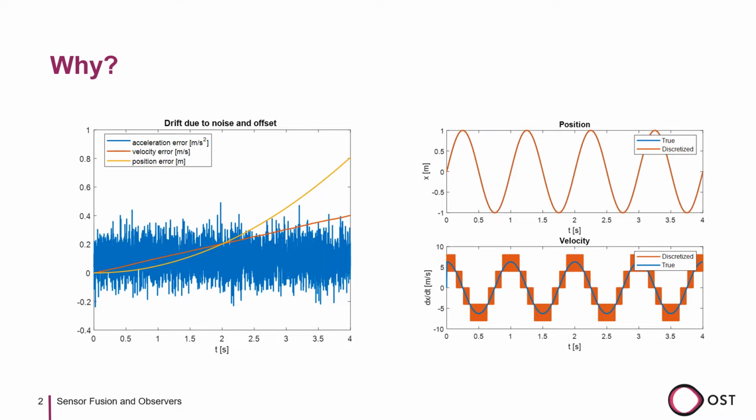As a last example, it could be that the bandwidth of the sensor signal is not high enough for our desired control frequency. As an example, if we get a new position from our GPS sensor every second, then we cannot use the signal to precisely control the robot's movement because we are essentially blind in between the new measurements.